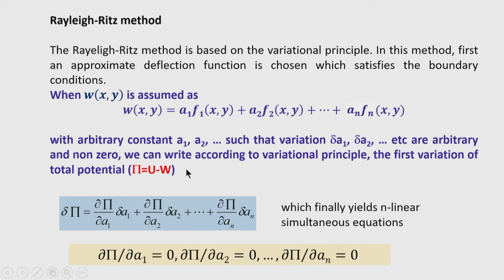You can see that the energy expression used for finding the total potential contains the deflection and the square of the deflection. Actually, energy is a positive quantity, so it contains the square of the deflection. So, the square terms, that is A 1 square, A 2 square, or the product of A 1 and A 2, will all be mixed up in the total potential.